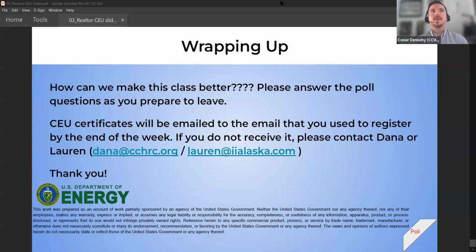But that's not on the homeowner maintenance side, and I would say that's pretty rare, because the way ductless heat pumps work, the units are relatively close together. So there aren't that many tubing connections to be made, and the more connections you make, the more leak points there are.